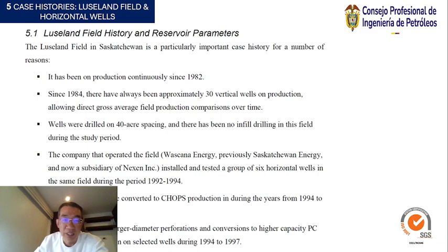Recompletions with larger diameter perforations and conversions to higher capacity PC pumps were undertaken on select wells during 1994 to 1997.